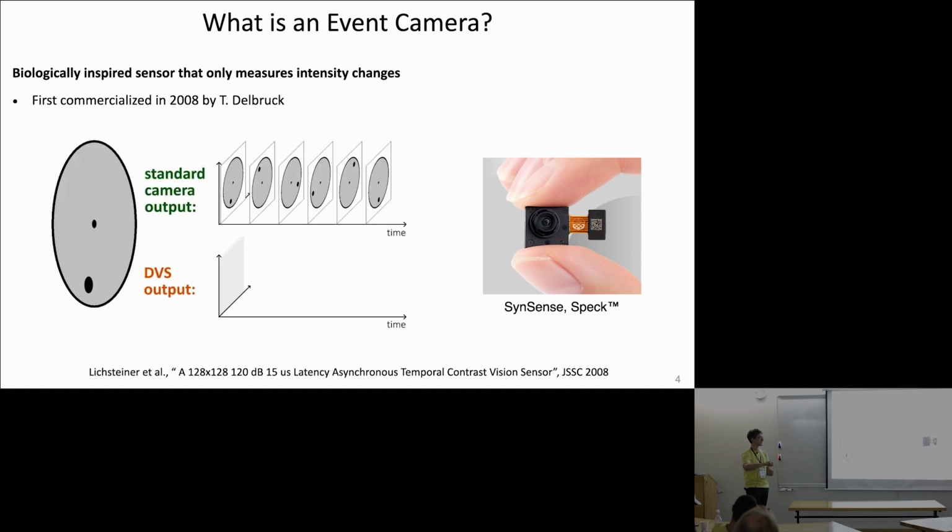This means that it's kind of low power, and usually people use this kind of hardware to accelerate event-based perception. Some chips, for example, include this Speck chip in particular, but there's also Intel Loihi, Loihi 1, 2, and then there's a larger chip, I forget the name, that combines several of them. Yeah, these are all available to do this processing.